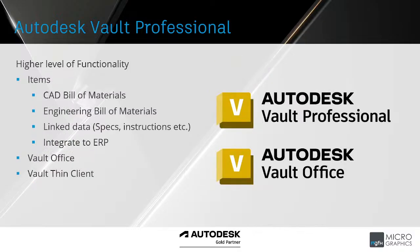Vault also has items. Essentially, items allow you to convert a design into an internal object that is linked to multiple files, but can also be exported out for ERP. So an item would be an object that shows you the CAD bill of materials, so the bill of materials pulled from the design from Inventor.